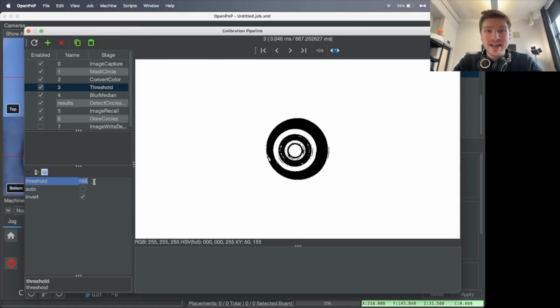Now I'm going to go ahead and change my threshold. So I'm going to make it a little bit more stringent. Let's set it to 200 and see what we find. That's the wrong direction. So I'm going to bring it back down to, let's say, 130. All right, might be a little overzealous. I actually think I want to bring it down to very low here and get a nice clean white circle.